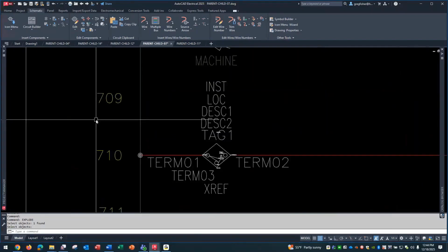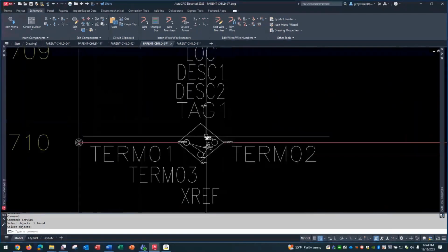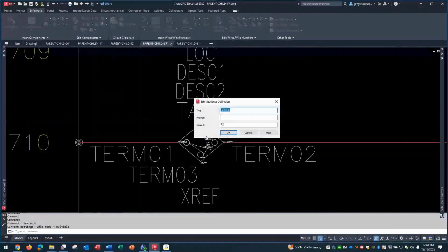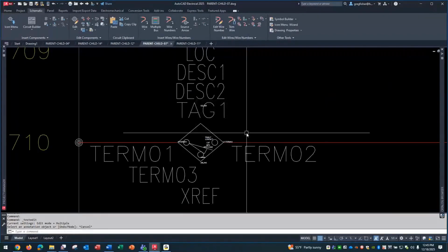Normal symbol. And again, it is tied to the table that you want to point to when you hit the lookup button. Can't stress that enough. In the symbol builder, make sure your table is pointing, through that family attribute, to the proper table.